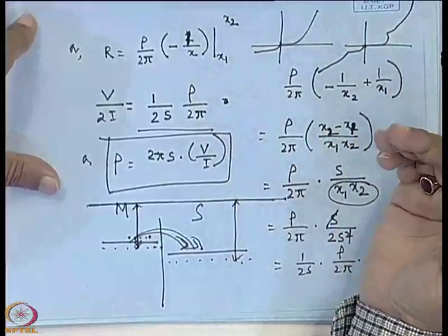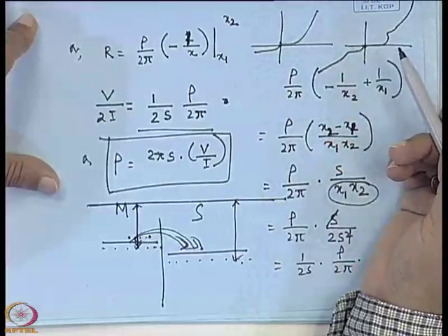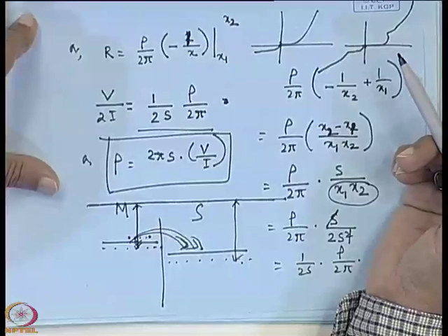Then we have to study what type of conduction it is, whether it is due to thermionic emission or generation recombination or some heterostructure type of conduction. There are many conduction mechanisms in semiconductors. One is ohmic, another is Schottky, but apart from that you can consider different kinds of mechanisms also, or a mixed mode conduction mechanism. In some cases hopping conduction takes place. So, there are various transport mechanisms in semiconductors, but those will be non-ohmic in nature.